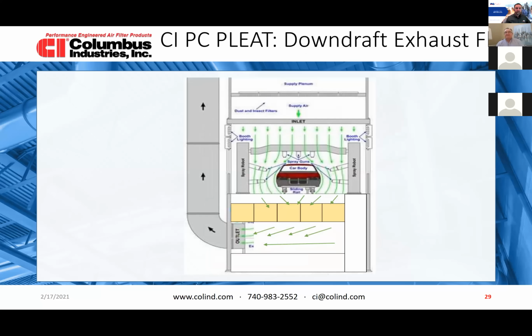So in this dry filtration, there were also efforts from other companies and from us to create this high capacity filter that we call the PC pleat. We first started by putting this in a floor, like a downdraft booth. So these are the boxes, and the whole floor under the grid would have these boxes. They're very low resistance, good efficiency filters. And again, you don't have to change them like you change the rolls every 2 days or 2 shifts. These would last longer, extended periods of time, 1 week to 2 weeks, depending on how much you're spraying.